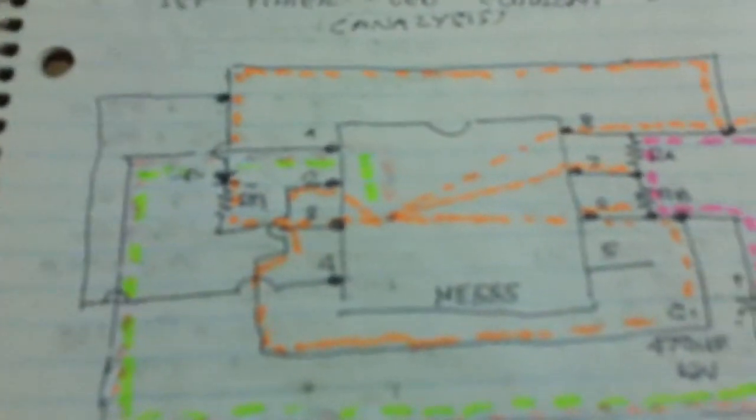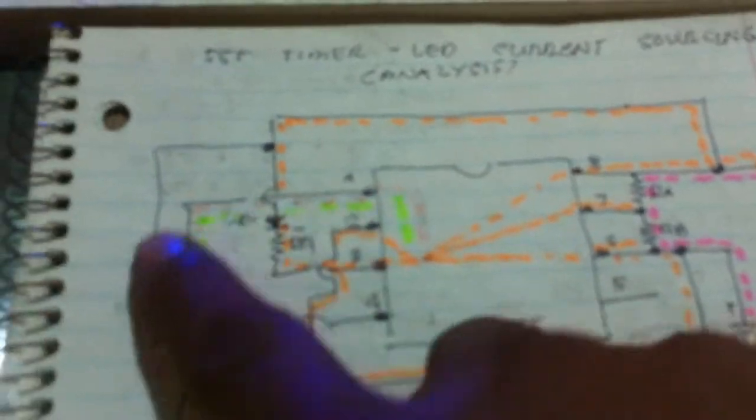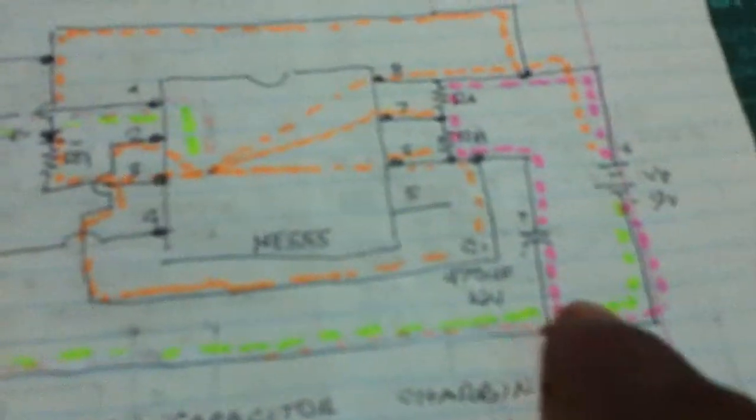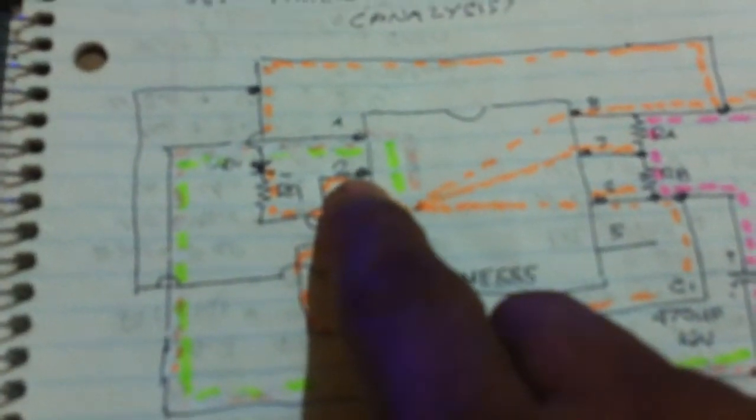So the equivalent of this old, previous circuit is this. We have pin 1 connected to the ground. Pin 2, that is the trigger, is connected to pin 6. Pin 3, the output. Then the cathode side is connected to the output, just like here. The cathode side is connected to pin 3.